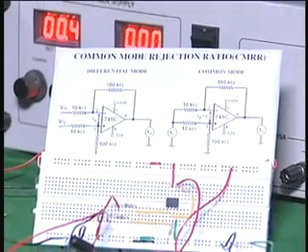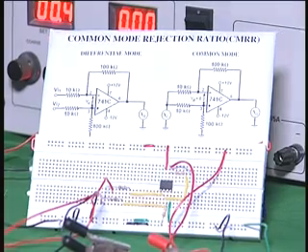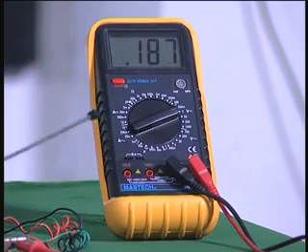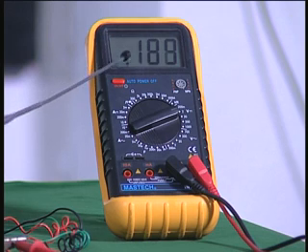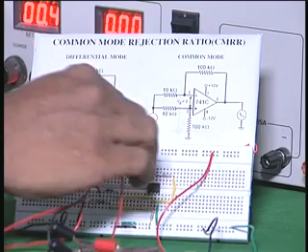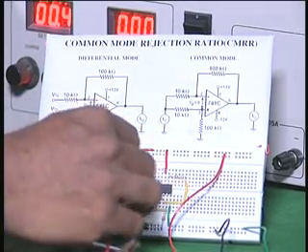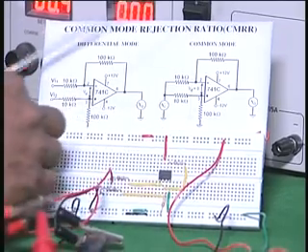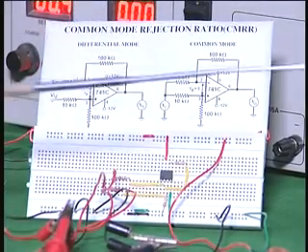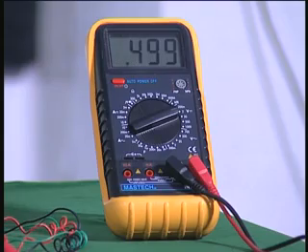Now, what I can do is first use the multimeter which is here. I will connect the multimeter to the two inputs and measure the voltage. So, I will ask you to concentrate on the voltmeter while I connect to the two inputs. Now, I take the multimeter and connect to one input terminal, you can see it is 0.5 volts, that is V1.